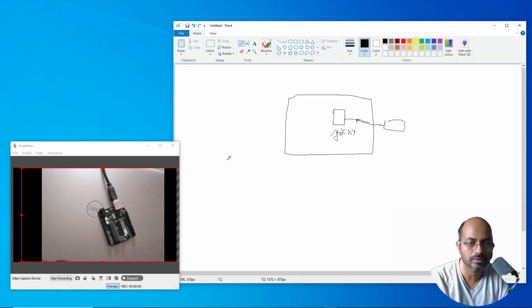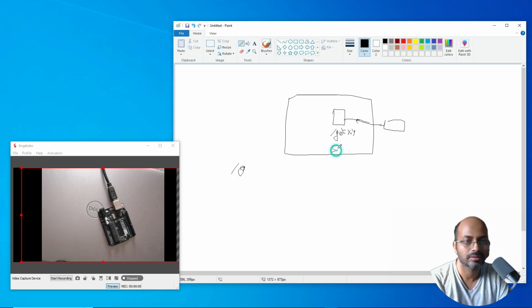So that means, sitting in this kind of framework, from anywhere, if I call get xy, whoever the client is, if he subscribed to this get xy, he will keep getting the xy location of the robot. And similarly, set xy will help you move the robot in any direction. So after you do that complicated sine theta, cos theta, and finally end up with some value that you want to move the car to, you just send a set xy, and you don't have to bother about how that is implemented.